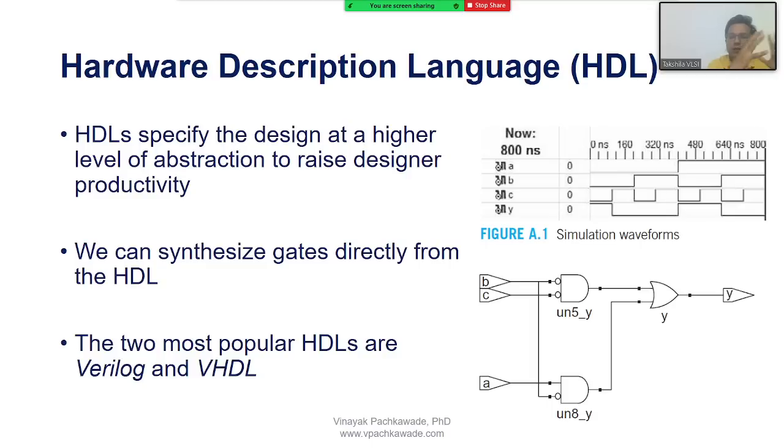Like I said, if there is a big chip at the system level, it would be partitioned into different blocks, and only one of those blocks, let's say, comes to you. Then your job is to do the physical design of that particular block. Let's say it's a controller block or data path or arithmetic logic unit, for example. So you will design that yourself. You will draw the mask for that particular module or cells, using the cells and the transistors you have knowledge about and the skills about.